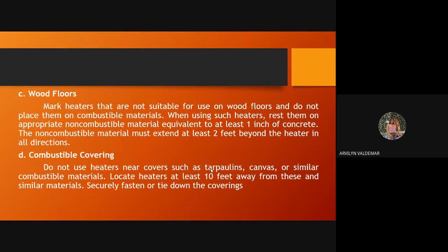So, for wood floors, mark heaters that are not suitable for use on wood floors and do not place them on combustible materials. When using such heaters, rest them on appropriate non-combustible material equivalent to at least 1 inch of concrete. The non-combustible material must extend at least 2 feet beyond the heater in all directions.